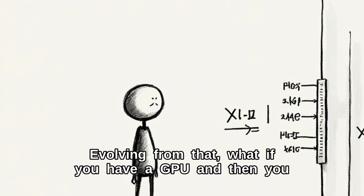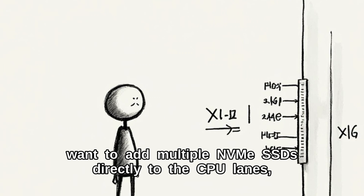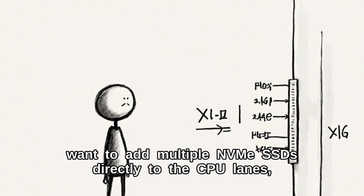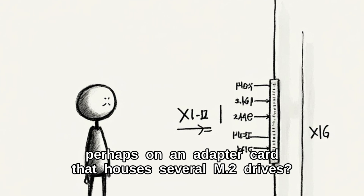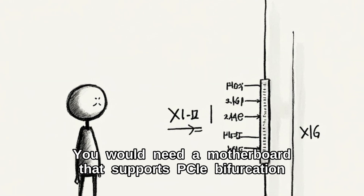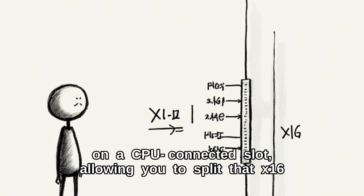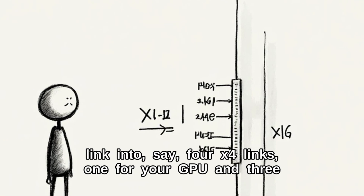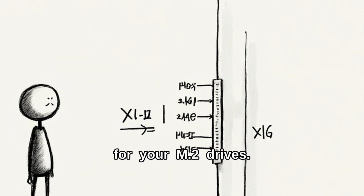Evolving from that, what if you have a GPU and then you want to add multiple NVMe SSDs directly to the CPU lanes, perhaps on an adapter card that houses several M.2 drives? You would need a motherboard that supports PCIe bifurcation on a CPU-connected slot, allowing you to split that X16 link into, say, 4 X4 links, 1 for your GPU and 3 for your M.2 drives.